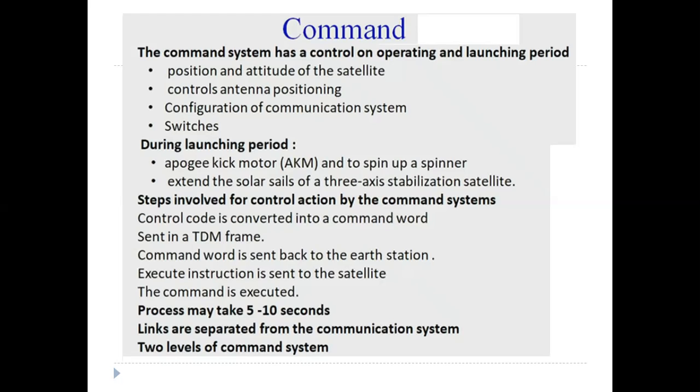The command structure must possess safeguards against unauthorized attempts to make changes to the satellite's operation, and also against the inadvertent operation of a control due to an error in the received command. Encryption of commands and responses is used to provide security in the command system. A typical system is shown in the figure that will originate the command at a control